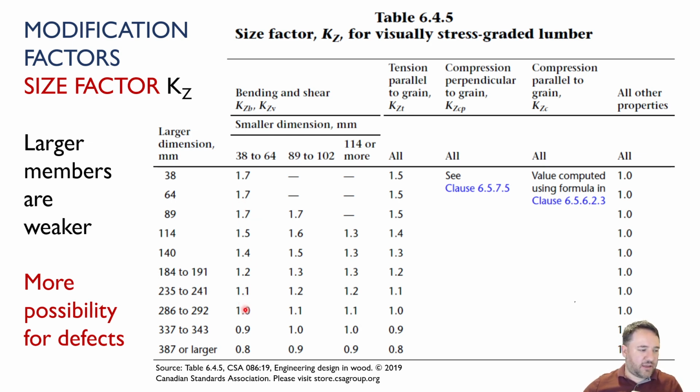Now these numbers are a bit arbitrary. They're based on a baseline. So basically, they did tests. The test pieces were this big, and then relative to that, they said, okay, what's the size of something that's this big? And they said, oh, it's 70% greater because the grading is better. So therefore, the factor is 1.7. So this is a function of where the strengths in the other tables are defined for. If I went to the strength tables, the baseline size for that strength is a certain size. And then relative to that, the strength can either go up and down depending on the size.